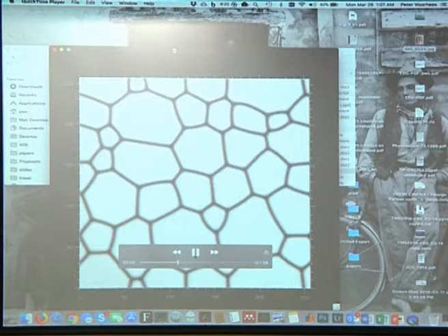And then the problem is that it's possible for 2 grains to be right next to each other that have precisely the same order parameter. And what you'll see is that since they have the same order parameter, they don't produce a grain boundary, and it just kind of disappears. And so there's all sorts of complicated algorithms that people have generated, and I think it's in the Moose code, where they set out a set of order parameters and they monitor the grains in the neighborhood to make sure that 2 adjoining grains never have the same value of the order parameter, so you don't have this idea of the grain suddenly disappearing at a boundary.